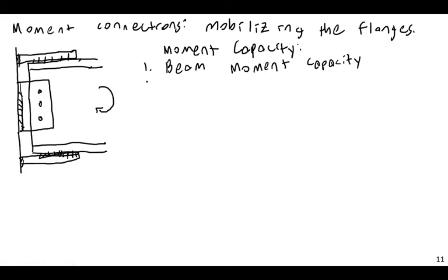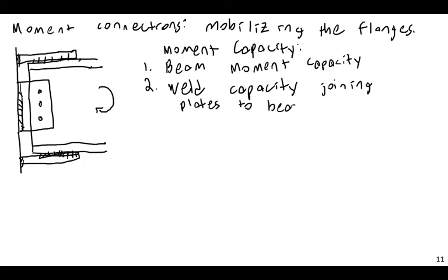Beam moment capacity. Two, the weld capacity, the weld capacity joining plates to beam. Three, the plates themselves, usually the tensile capacity.